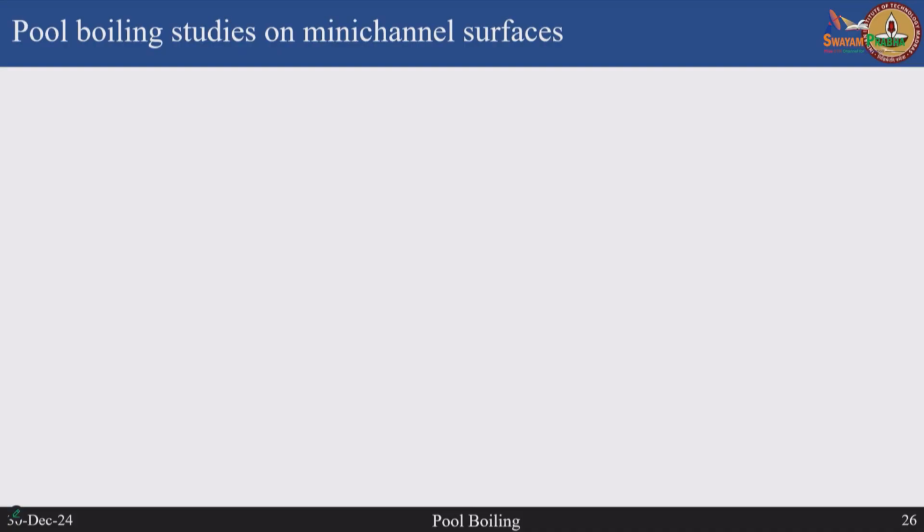For example, people are looking at porous structures, where these pores have a very specified void fraction or porosity, which can control these nucleation processes. And people were also using fins or micro fins or mini channel fins to look at how the nucleation is influenced.